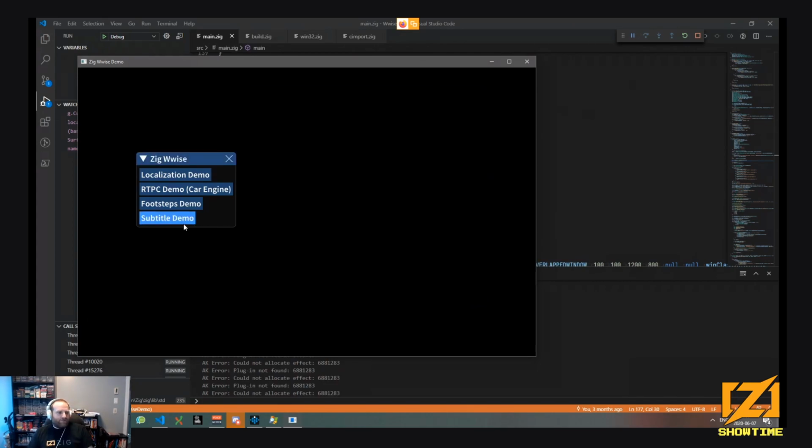And the last one I did is a subtitle demo. You can put markers inside a WAV file and add subtitle information if you want. When you play an event in Wwise, you can register for callbacks for info. So you can get the marker info. If you play music, you can get the beats per minute and do crazy stuff with the music. And you can also get an event when the event is finished playing.